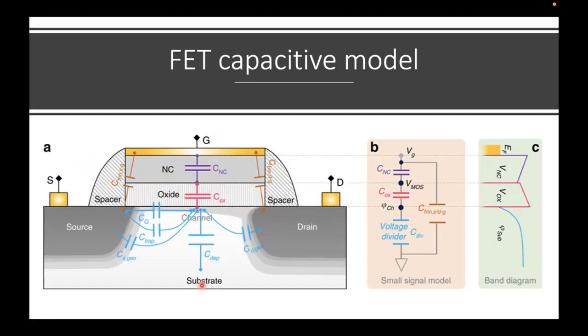So we build an N-channel MOSFET on a P substrate, leading to a PN junction here, creating a very important and critical capacitance in the MOSFET, which we call the depletion capacitance. Again, we have another PN junction because our drain is an N and our substrate is a P. So we have a PN junction capacitance here, and we have a PN junction capacitance there.